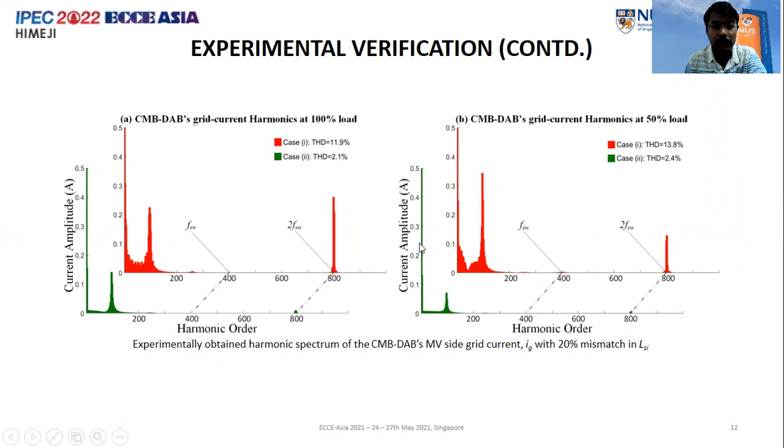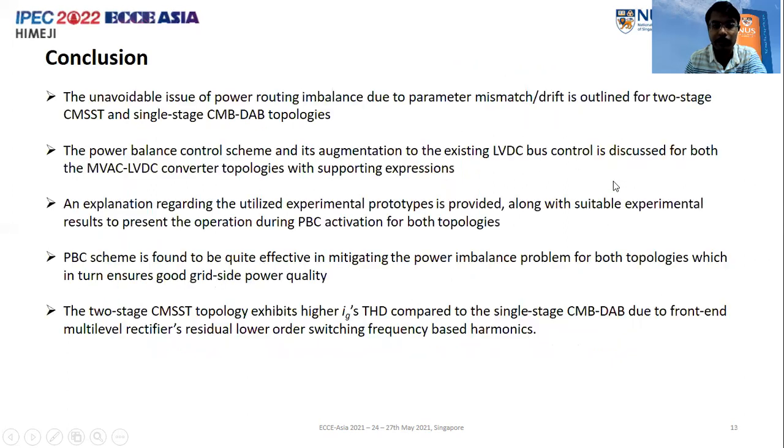There, I think you would also see a peak near the lower order, which might cause a doubt in your mind, but that is the resonant frequency of the half bridge submodules' capacitor and the filter inductor. So that is a filter resonance effect, which is also of very low magnitude. So that is not a major issue, and we can see the THDs are dropping to below 2.5%.